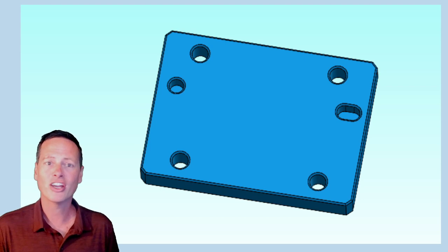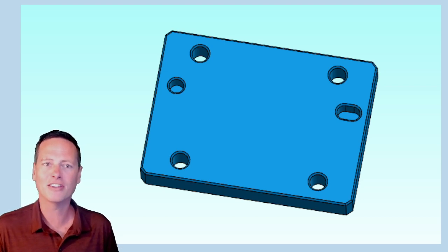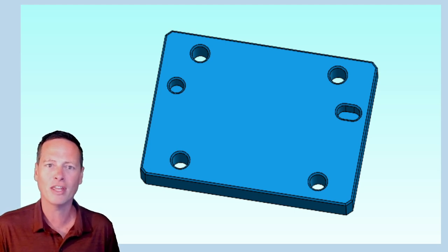But I'm like, what is even the point of translating datum modifier if you can't use perpendicularity to calculate MMB? This is not how you want to start a conversation at a party, by the way. But look, this is the same reason we use a slot in the part that locates onto these pins. We can make that slot a close fit on the pin, improving the repeatability of the assembly. Okay, so unless I'm totally missing something, this is crazy cuckoo bananas, because now I'm thinking that I have to do some unusual stuff to fix the situation.